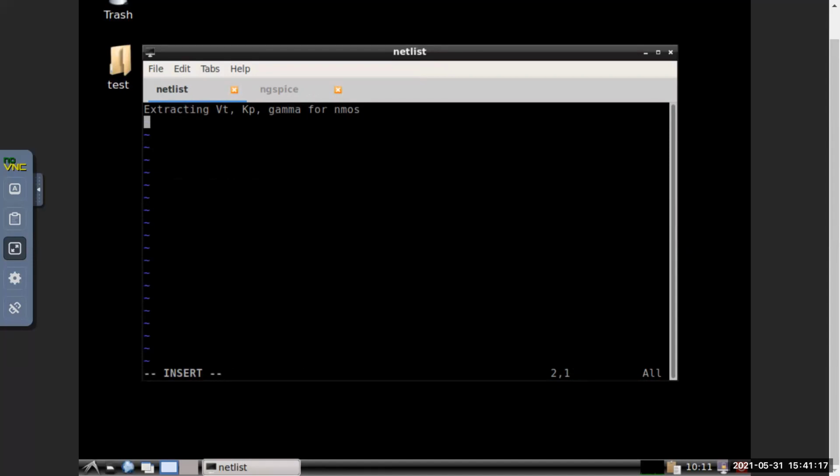Now what should be the next one? Today we'll try to add comments as much as we can, to make your programs readable. The first line in NGSPICE, you can either give an asterisk or not, it doesn't matter, it'll automatically be taken as a title. But from then on, if you want to give a comment, you have to start with the star or asterisk. So first thing, what should we do? We should call the library file, or include the library. Include the SCMOS library.